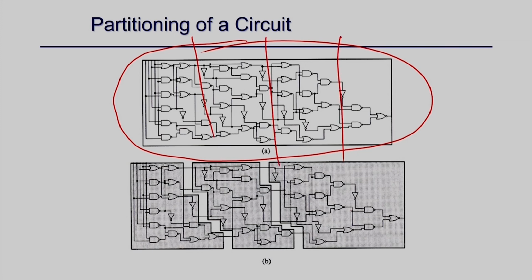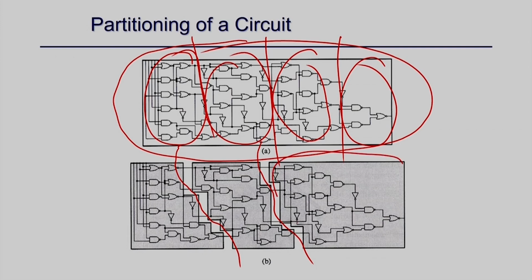So you partition your design into small components, and you place this together, this together, this together, something like this, right. Similarly, what is shown here is a partitioning with 3 partitions, and I try to place each partition independently. Once that is done, I can recursively do the same partitioning within this component or this component, until I have a module which is easy to handle, right. So this is what partitioning of a circuit means.